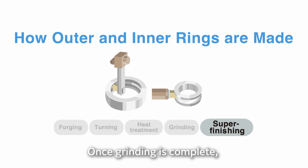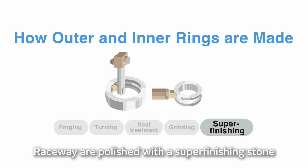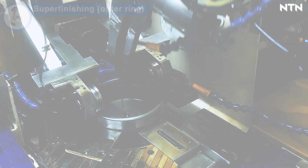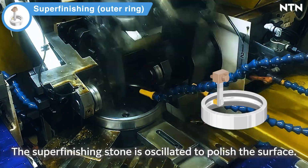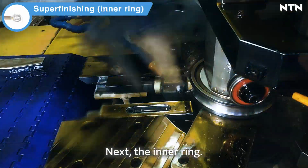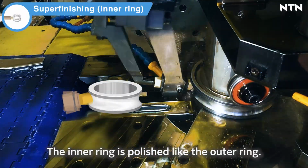Once grinding is complete, it's time to super finish the raceway. Raceways are polished with a super finishing stone to achieve a smooth surface. First, the outer ring. The super finishing stone is oscillated to polish the surface. Next, the inner ring. The inner ring is polished like the outer ring.